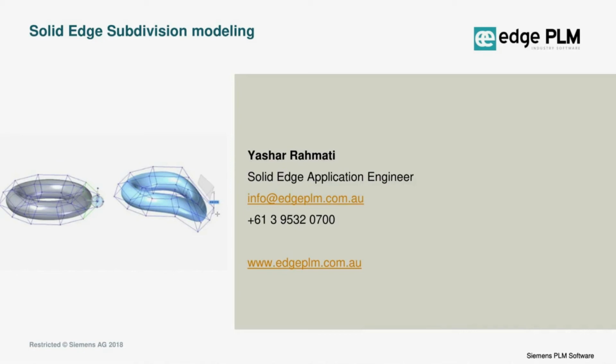It's based on some basic shapes that we use to start with. In subdivision modeling, users can subdivide the basic shape into some cage vertices, and then you can drag the edges, the nodes or areas of your basic shape in order to achieve the complex shape that you would like to design and create.